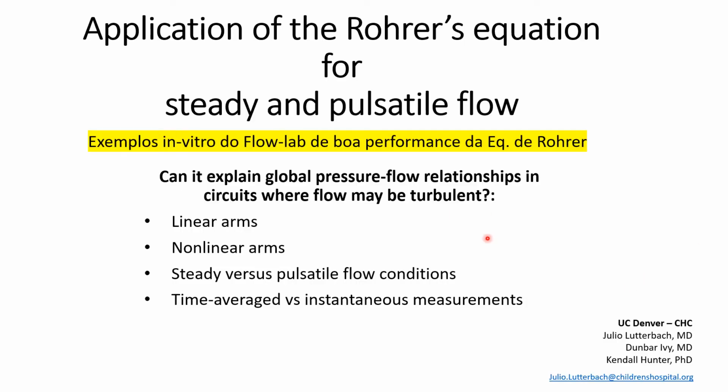So what I did, I went to the flow lab here at UC Denver with the orientation of Kendall Hunter, and we built arms on the circuit that have a linear behavior, like Poiseuille's law, and then nonlinear, which is more like a stenosis. We studied that with a steady flow situation, and then put a Harvard heart pump simulator to reproduce the pulsatile flow conditions. And we got the time-average data and also instantaneous measurements.